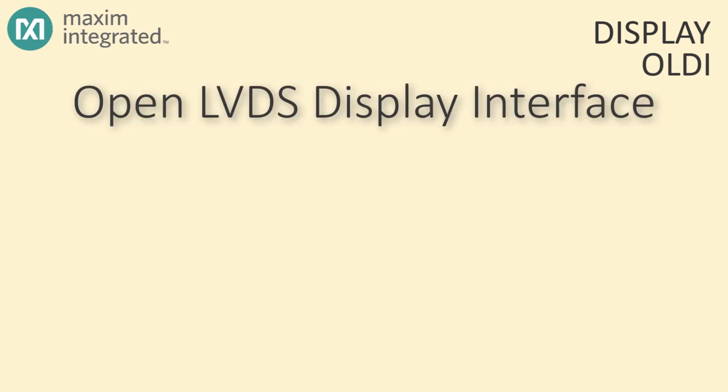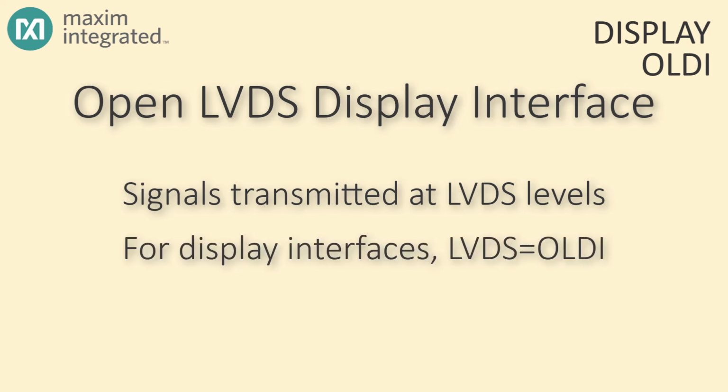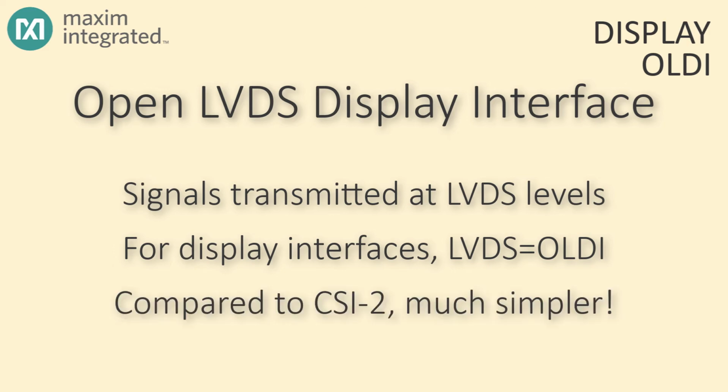Alright, now let's look at OLDI. It's a display interface. The letters stand for Open LVDS Display Interface. And yes, the physical layer is based on well-known LVDS levels. Now, in fact, you'll often hear engineers talk about an LVDS video interface. Well, that's OLDI.